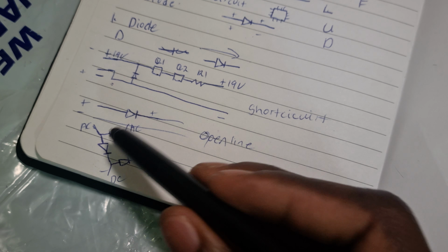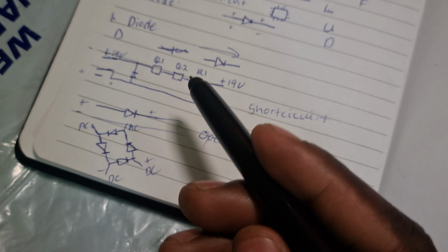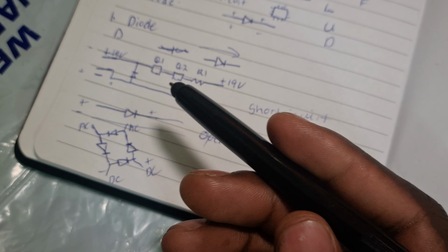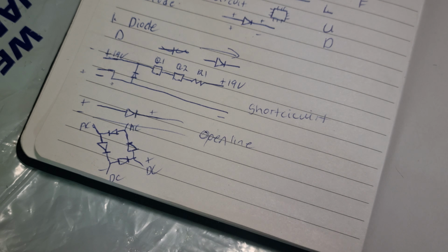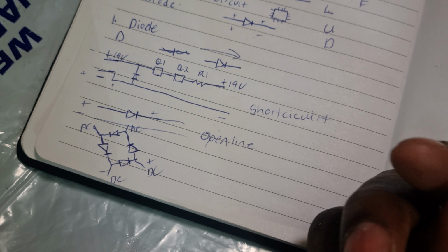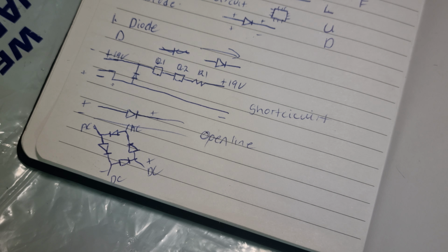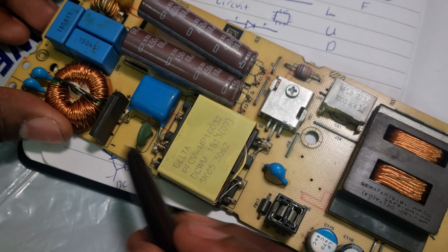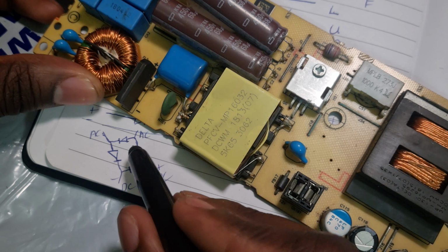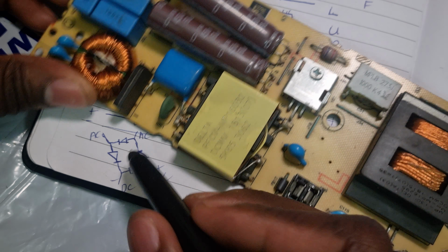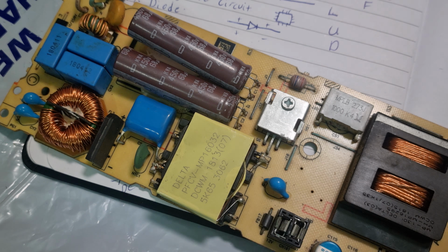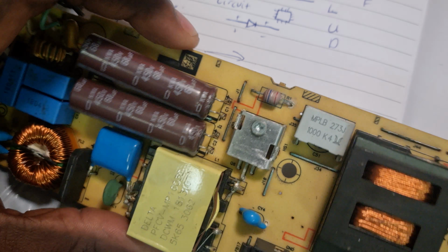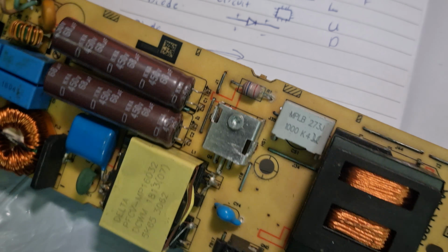You get 4 diodes. If one of them fails, your bridge rectifier doesn't work. They're the ones that convert your voltage from AC to DC. So one application will be this. This is a PlayStation 4 Slim power supply, and that's a bridge rectifier. Inside this, you've got this circuit, 4 diodes inside this thing. That's a bridge rectifier. That's its application. Let me see where else they apply the diode.